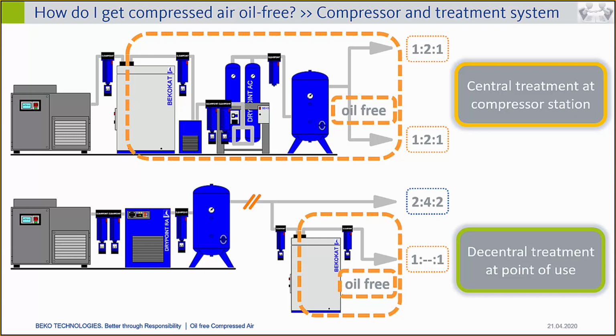Please always have a look at the suction conditions on site. If that is, for example, an area where frequently a huge amount of dust will appear, I would also recommend to put an additional filter. Yeah, but then a coarse filter, so a 25 micron filter would be good enough, I would say. Some people may recommend a different quality class of filter, but that would be okay.